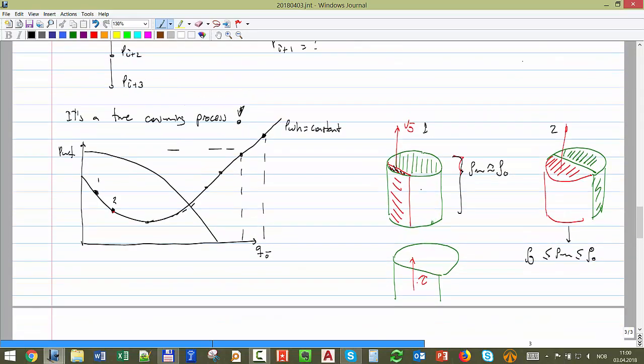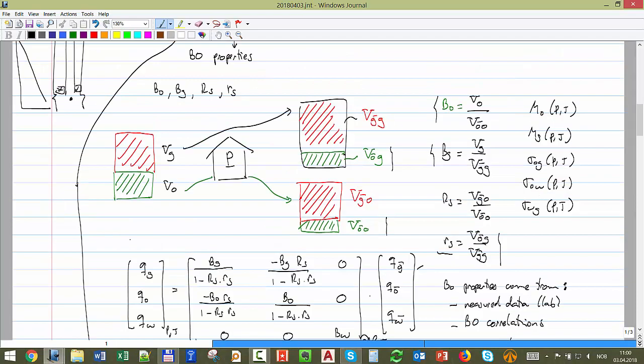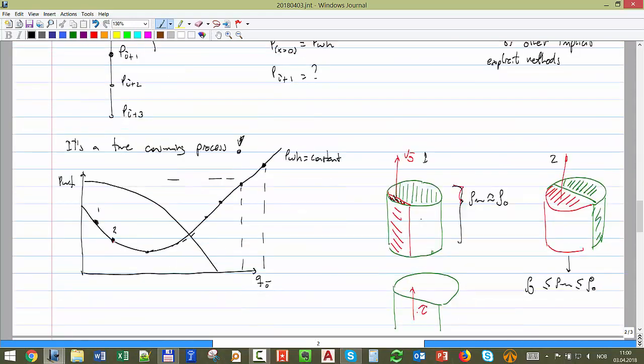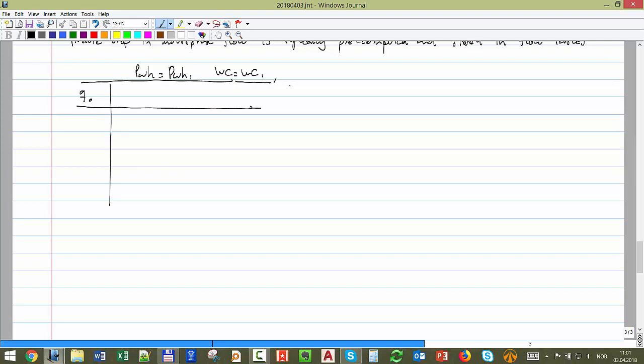Because of that process, we need to have access to this expert, we need to have access to properties, and that might be a hassle. The way we make it is that we pre-compute a lot of conditions. So, for example, the way the table looks like is I fix wellhead pressure, P wellhead 1, and then I calculate for different rates Q oil, and here is also water cut 1, and GOR equal to GOR1.